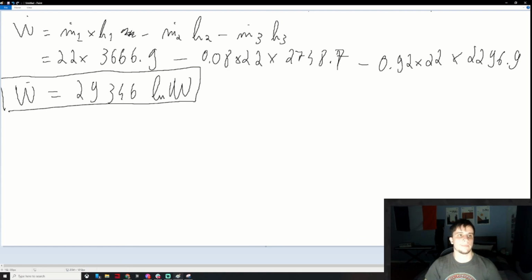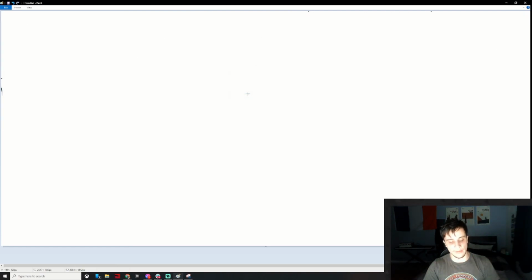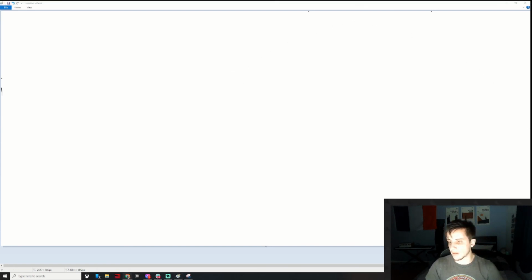Voila. So that was the only tricky part about this exercise, was just the fact that it separates, pretty much. You have to make sure that you take into account the sum of the energy change in the exit. So you add the two internal energy changes as we had in this exercise, and also taking into account the mass change as well. Those are the two, I guess, important aspects of this.